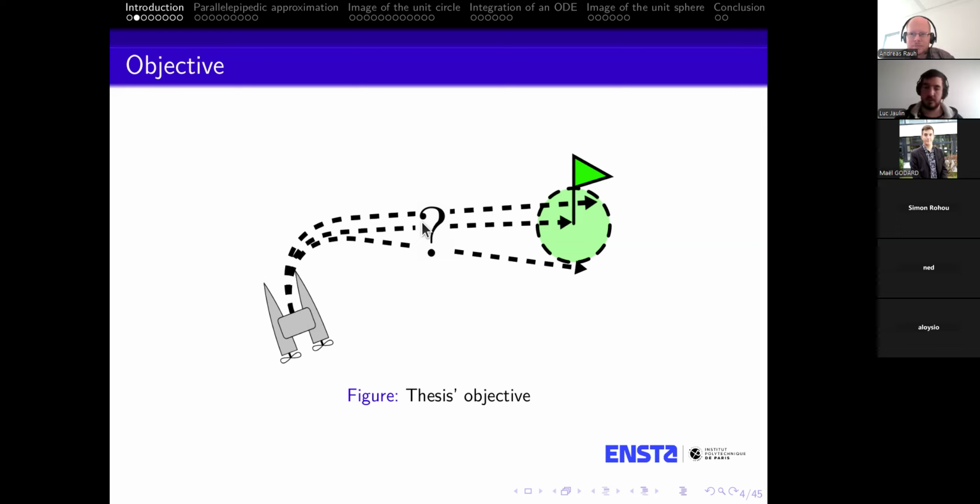By doing so, if I have my robot at a given position initially, and I want it to reach a certain position, there is only one control going from this state to the position. So before the mission, I'm able to say that the control will be this, and it's purely temporal. So this is the first step. We're not yet at the autonomous part because there is no sensor and no loop. It will be purely open loop, but I think it's a fair first step towards reachability.